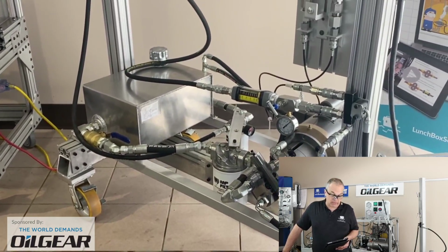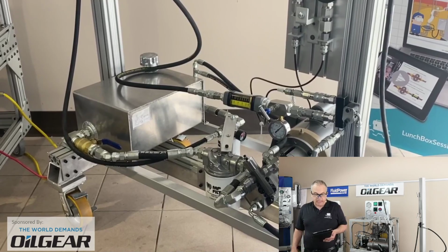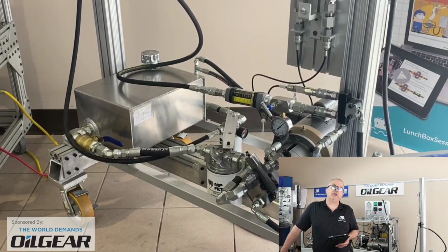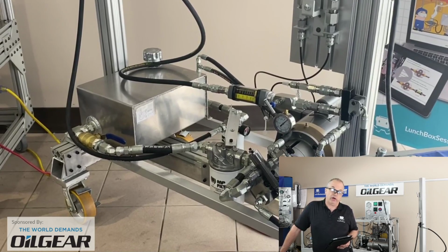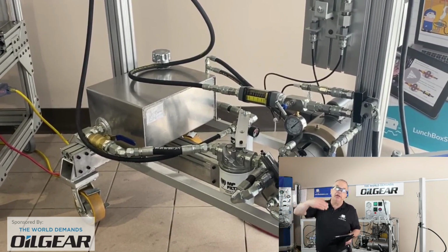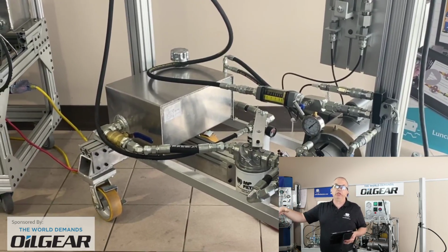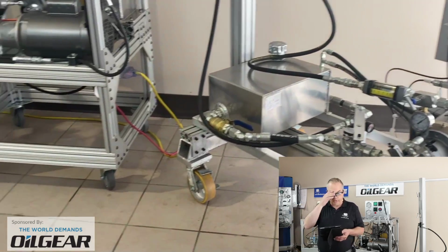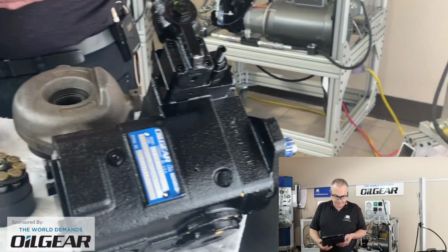Usually, even, I see you asked about a closed loop system. Yeah, but case drain flow usually has to be left uninterrupted on its way back to tank, and if additional cooling is needed, then typically another kidney loop pumping unit is involved, drawing fluid out of the tank and through a cooler for that. Great question though.